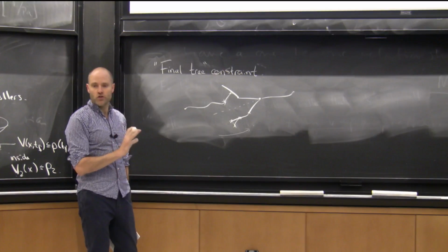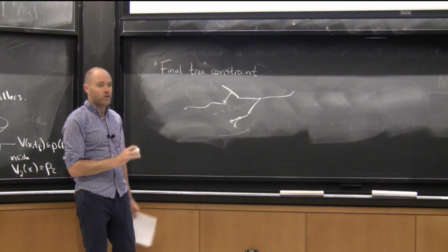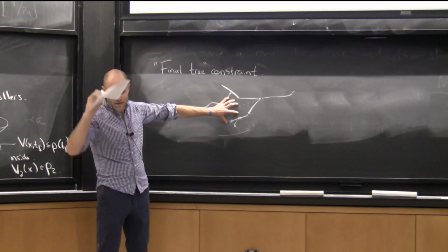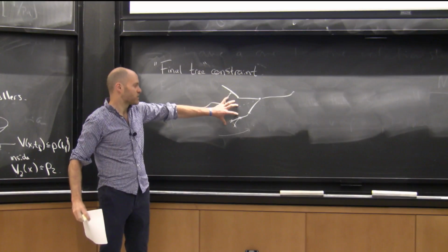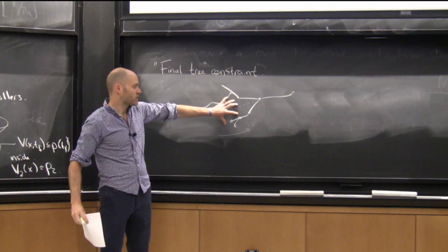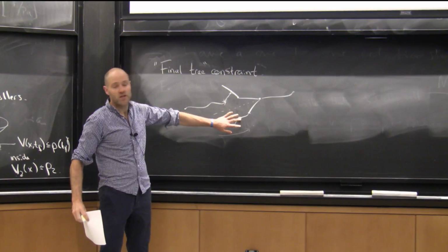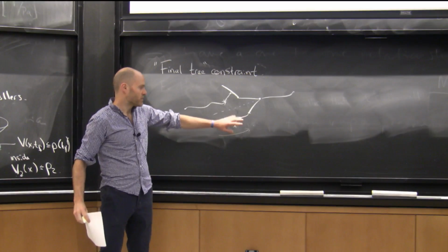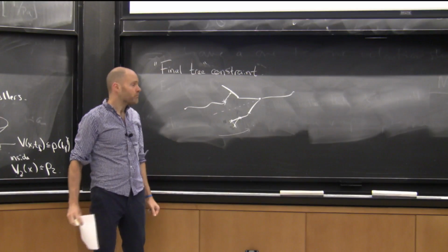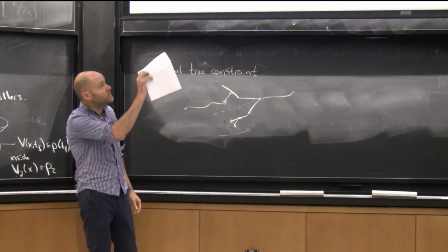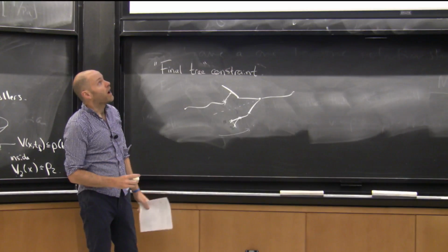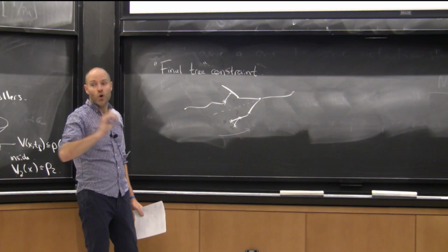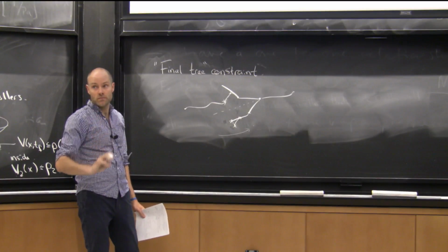So even if you're just doing motion planning for an underactuated system, this is one of the things I would have recommended in the laundry list of things you can do to make it work better for underactuated systems: using trajectory optimization to connect. It's just expensive, but it works well. It'll overcome the dynamic constraints. Okay, but for LQR trees, for this algorithm, it becomes essential to use trajectory optimization because you have to connect over a non-trivial distance.